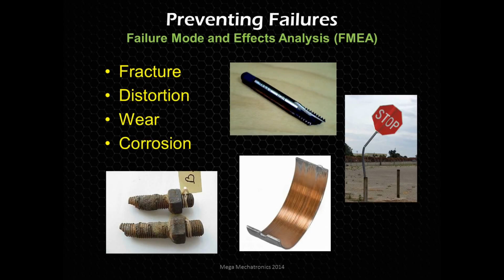What happened there? Was there galvanic corrosion? Were there dissimilar metals? Did the paint chip off? Did you not paint it? What type of environment? Was it designed for fresh water but was brought to salt water? And things like that. So you need to find that root cause. Why did it fail? Why did it wear? It broke, but it broke because of this and this. And going down the line, it started pitting. The material was defective.